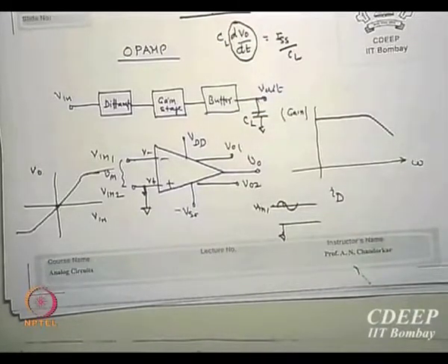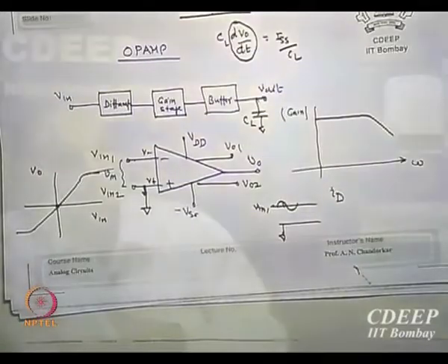So if you want larger slew rates, which you will require for high speed performance in connections, then you must have larger currents. But if you have a larger current, your diff amp stage will have lower gains. Is that correct? So this thing which I have not yet told you about the op-amp, that the last stage has to be connected, that may finally tell me how much ISS I will be allowed, because someone will specify it to you.